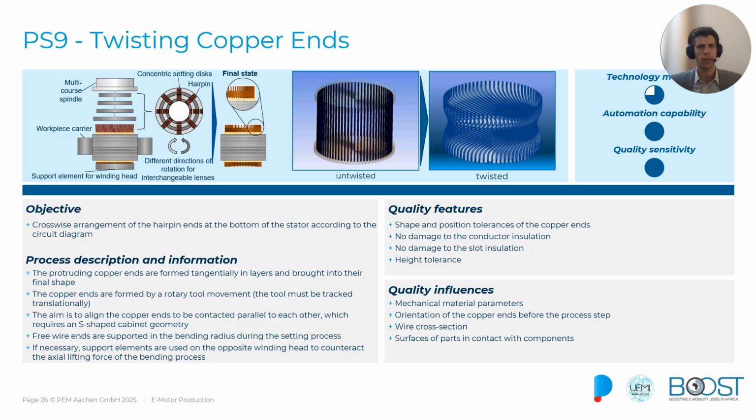The rotation is typically achieved using a machine that grips and twists the hairpin ends together, ensuring they are tightly connected and properly aligned for optimal electrical flow and subsequent welding.